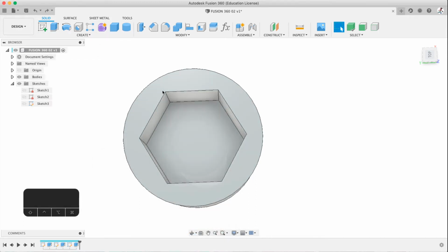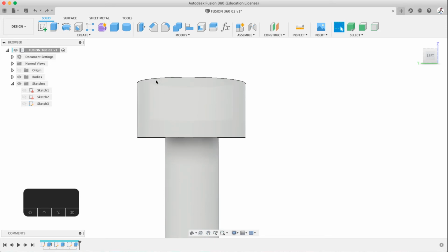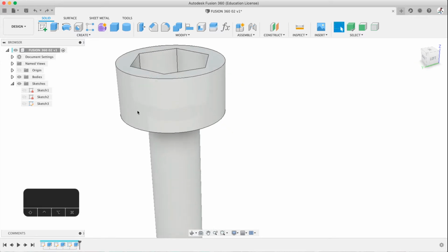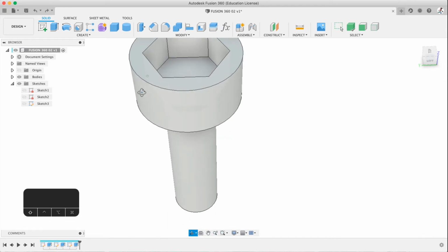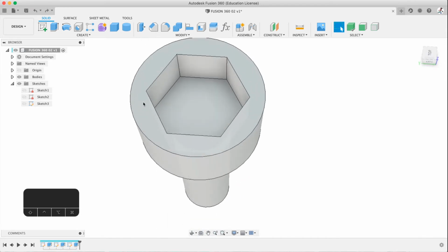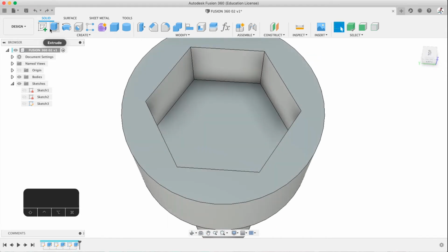So what we should do first is create our little ridges, because if you look at these type of bolts, they are quite tall with the Allen insert, and they have a kind of a hard ridge, a grip around the outside. It's a vertical line grip. It's not a, I forget what it's called, the cutouts where it's little diamonds cut out on the side of it. It's a vertical ridge. So what we will do is create a new sketch.